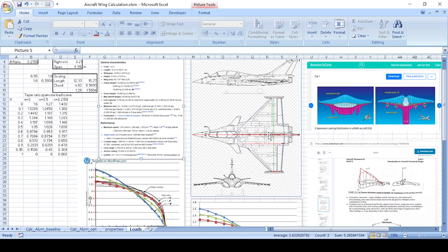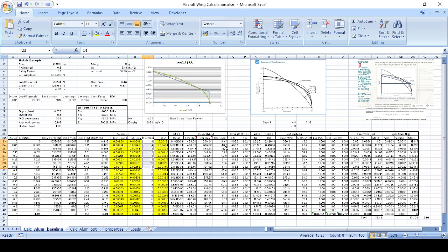What you would normally do is calculate your bending load and your shear load, and then do an interaction equation to calculate a new RF, but it's really complicated, so I've not bothered doing that for this exercise. This is a very basic spreadsheet. You can expand it and make it as complicated as you like; it's just to get people started. So from here you can see that I've got the weight of 256.